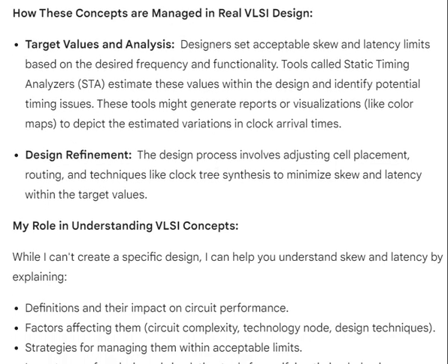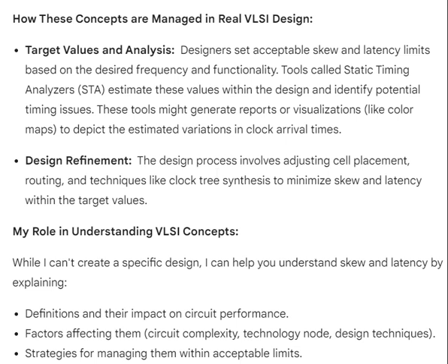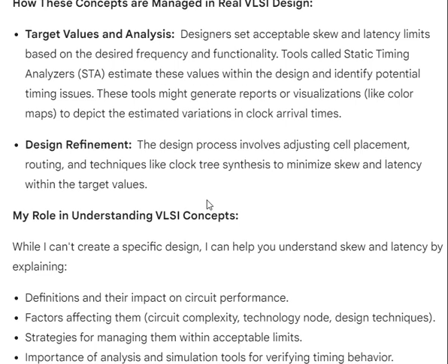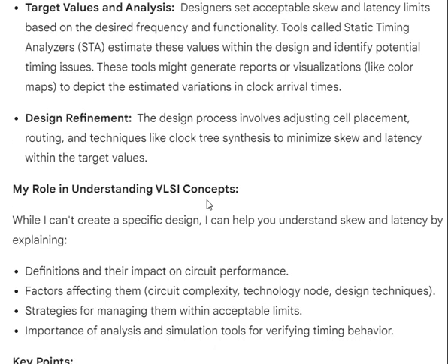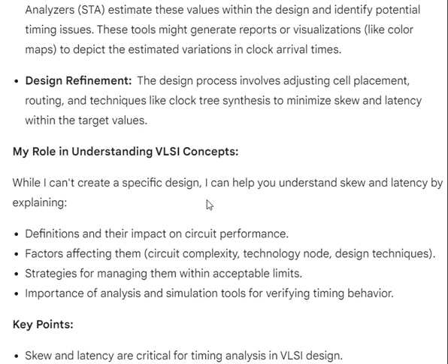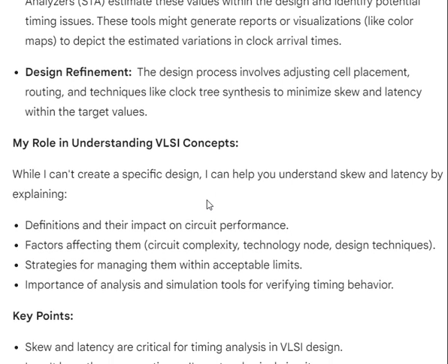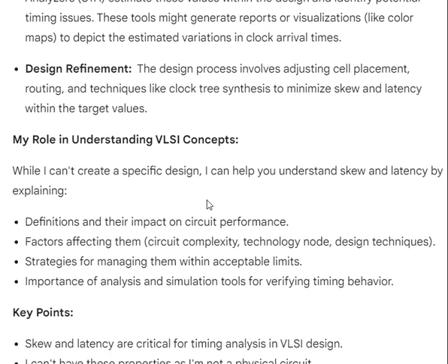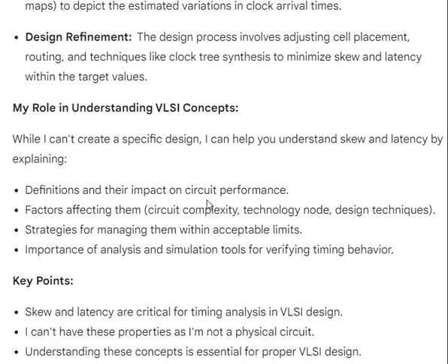How these concepts are managed in real VLSI design. Target values and analysis. Designers set acceptable skew and latency limits based on the desired frequency and functionality. Tools called static timing analyzers, STA, estimate these values within the design and identify potential timing issues. These tools might generate reports or visualizations, like color maps, to depict the estimated variations in clock arrival times. Design refinement. The design process involves adjusting cell placement, routing, and techniques like clock tree synthesis to minimize skew and latency within the target values.